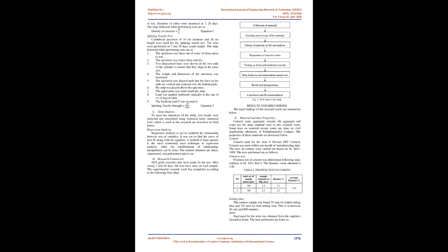Ceramic wastes can be separated in two categories in accordance with the source of raw materials. The first one is all fired wastes generated by the structural ceramic factories that use only red pastes to manufacture their products, such as brick, blocks, and roof tiles. The second one is all fired waste produced in stoneware ceramics such as wall and floor tiles and sanitary ware. These producers use red and white pastes. Nevertheless, the usage of white paste is more frequent and much higher in volume.